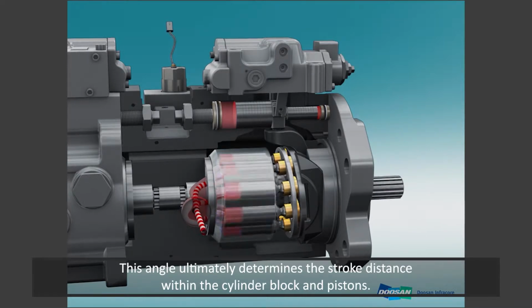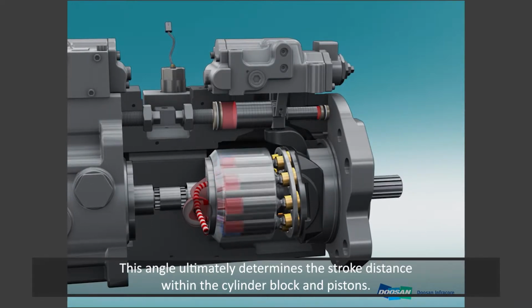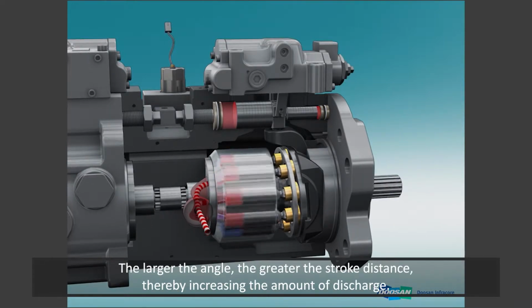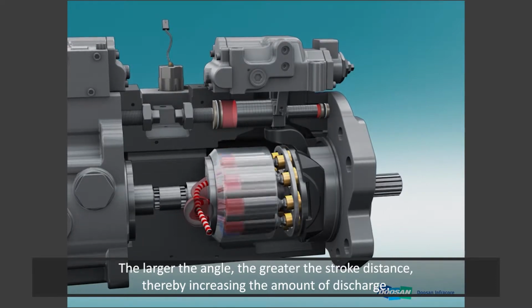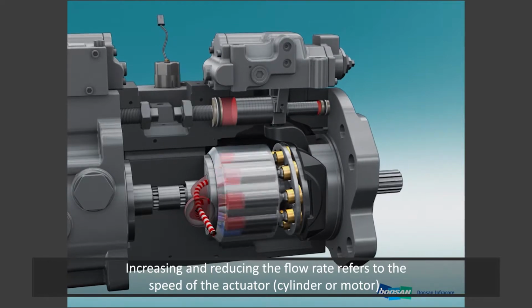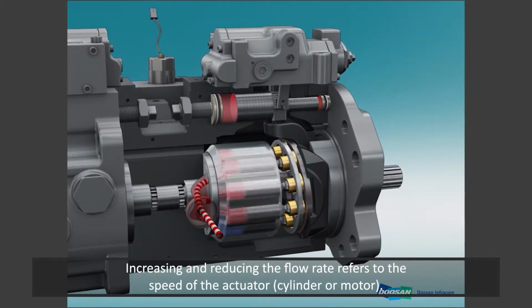This angle ultimately determines the stroke distance within the cylinder block and piston. The larger the angle, the greater the stroke distance, thereby increasing the amount of discharge. Increasing and reducing the flow rate refers to the speed of the actuator, cylinder or motor.